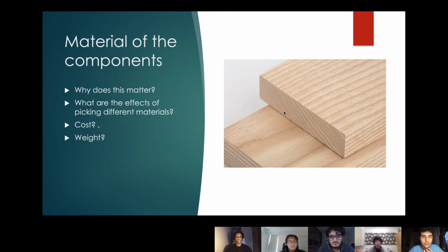There are three main talking points we had on choosing the materials. The main material had to be cheap, easy to customize, and strong. We found the perfect balance in Ashwood. It was relatively cheap, strong enough to make the gears from, and easy to customize with a saw. The only place where we thought the strength was more important than the cost is the axle. We used an aluminum rod for the axle as it is stronger than wood but cheaper than steel.